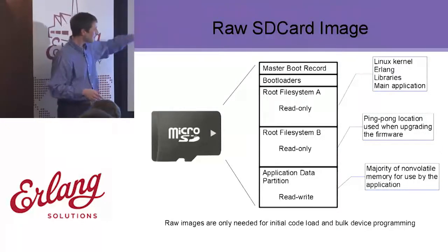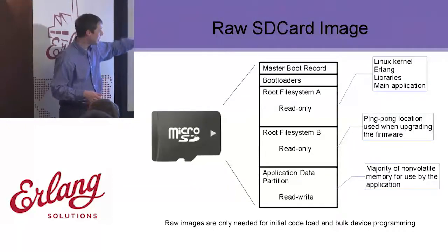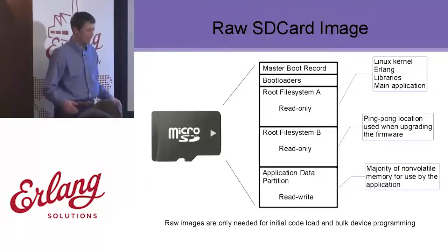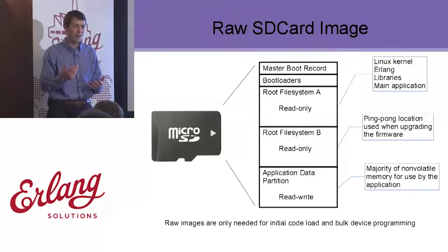So that's the idea. The other part is where the application writes data. I have a special partition for that. And there's kind of a logic here. With embedded devices, you really don't want to screw up the root file system because the people using it don't really have recovery tools. You screw up the root file system, the thing doesn't boot maybe, or it does something funny.